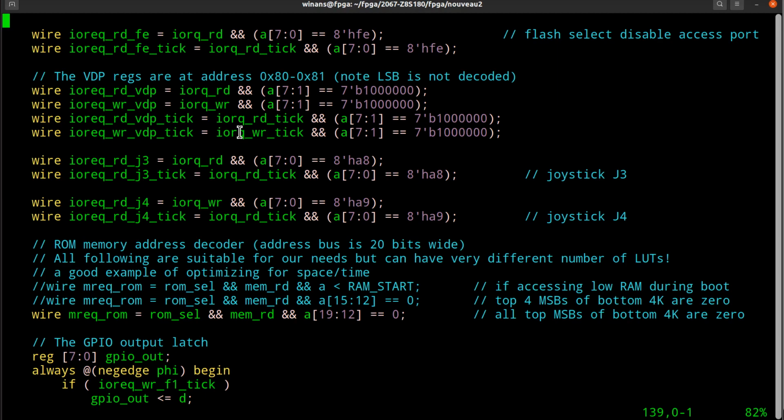I need to make sure that the implementation of that chip, that design in my FPGA, will consume data and provide data and get a single clock tick each time an I/O transfer is done. Down here, notice this is a 7-bit address I express in binary, not the full 8-bit like I do above, because this actually resolves the two adjacent ports. This is port 80 and 81, so look closely. I don't want you to get confused about that.